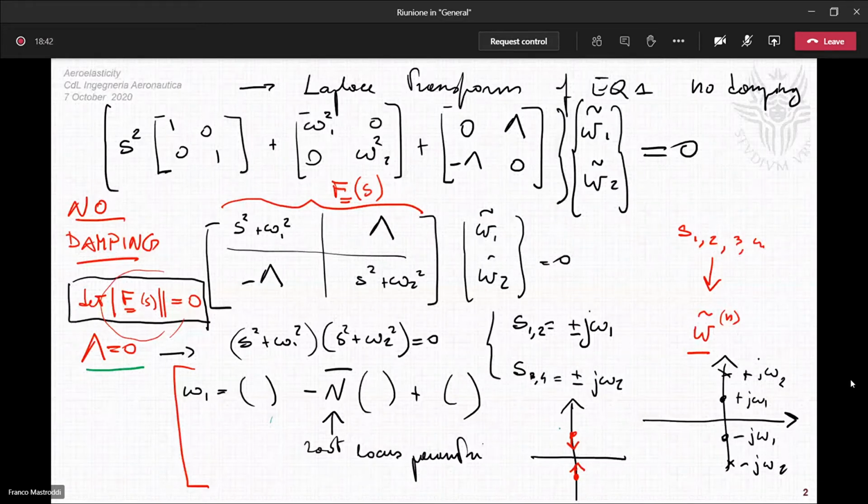And if you want, in this case, discuss the stability, but not the elastic stability, the buckling stability, you can do this because we are considering only a pushing force, lateral force, and therefore this parameter, n bar parameter, can be considered also as a stability parameter for the buckling stability.